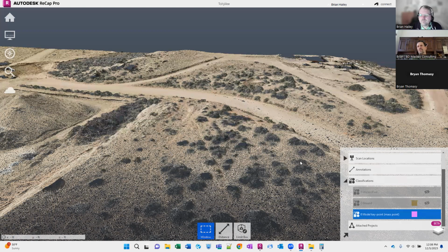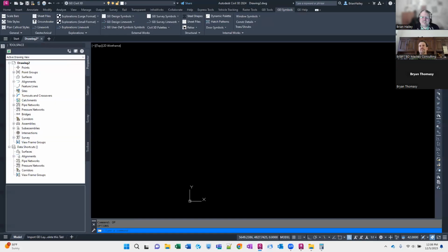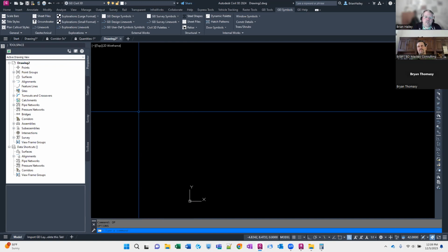All right. So Greg has a question. It's been a while since I've done line and curve tables, but when I have done them in the past, I place the tag numbers and the numbers jump and are not consecutive. The line tag starts off fine, 1, 2, 3, 4, but then skips a number, 1, 2, 5, 8, etc. Do you have a fix for this? Yeah. So you're using the default styles that come with Civil 3D. So whoever it was that created the default table styles for line and curves.